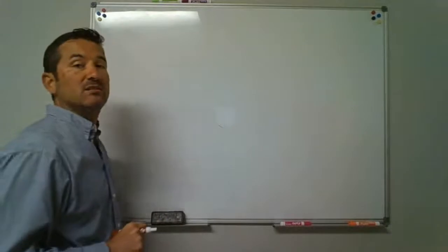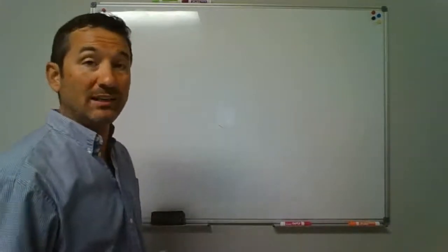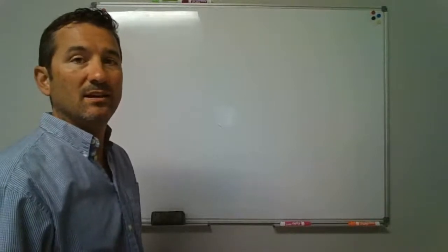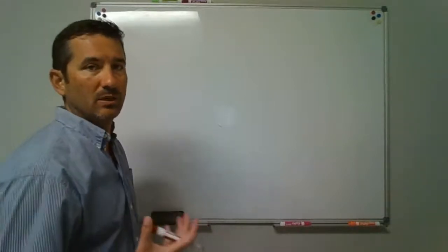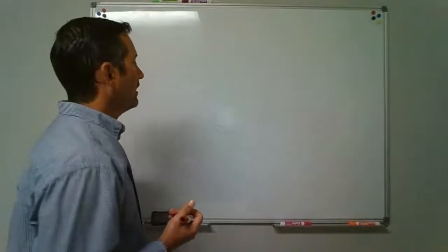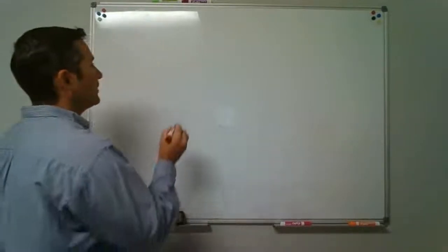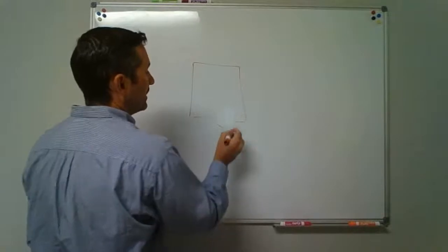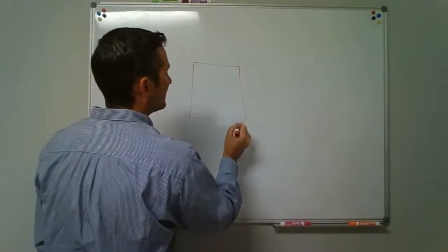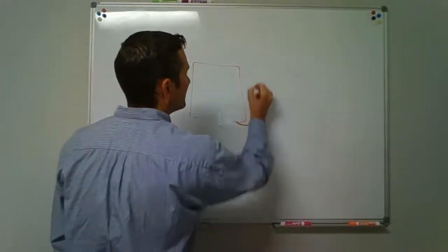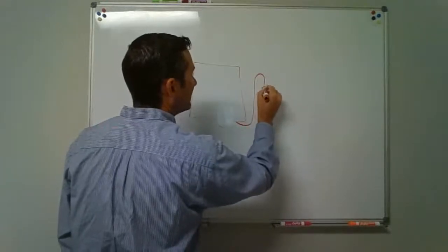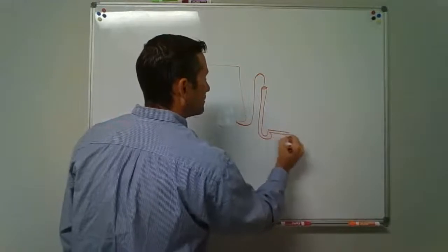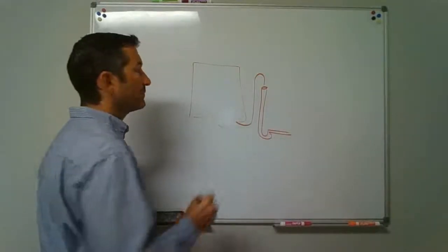A lot of these lines are installed incorrectly, and if you've got one at the house, you could just take a look at it and see, hey, did this get installed correctly or not? So what it says is, one, we could have a dishwashing machine that goes in, and we could take the drainage line off of that and feed in to a standpipe, just like our clothes washer does.